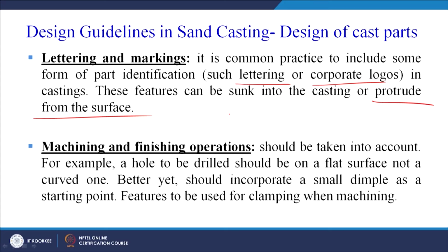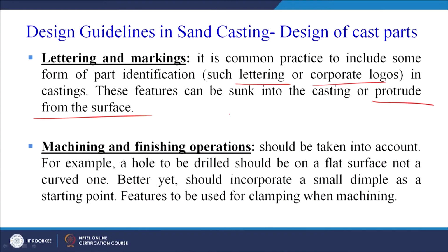For example, a hole to be drilled should be on a flat surface, not on a curved one. This we will also cover when we talk about the manufacturing design guidelines for machining processes. Better yet, it should incorporate a small dimple as a starting point. Why is a small dimple required?